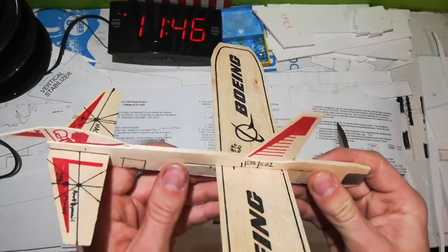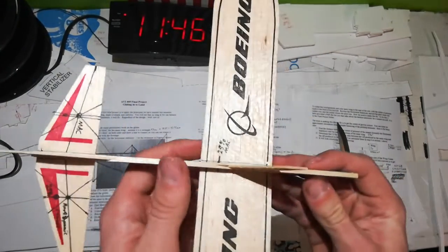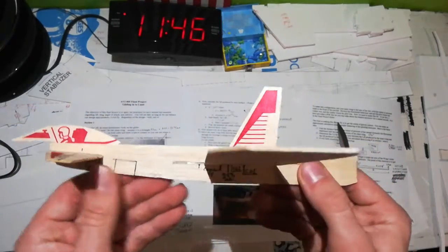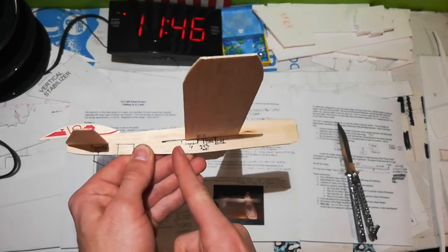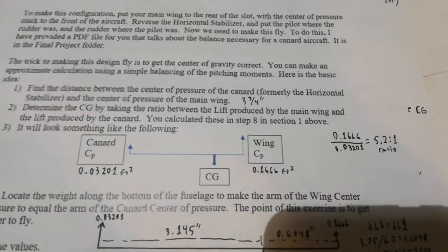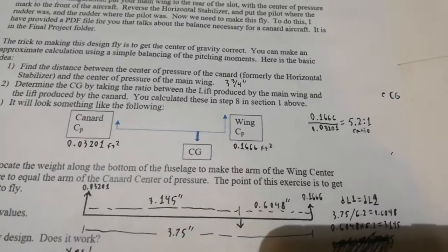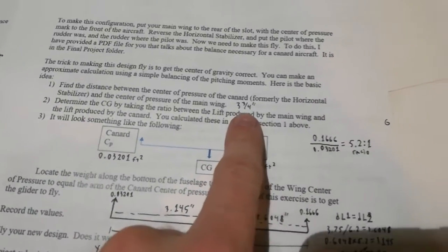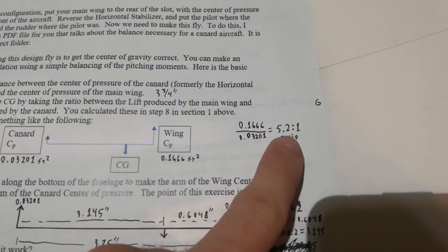So as we can see now, the center of gravity will have obviously moved, without this weight, that is. The center of gravity should now be right here, just forward of the wing. And we actually can calculate that. Here I measured the distance between the front canard center of pressure and the rear wing center of pressure, and it was 3.75 inches. And that is a ratio of 5.2 to 1